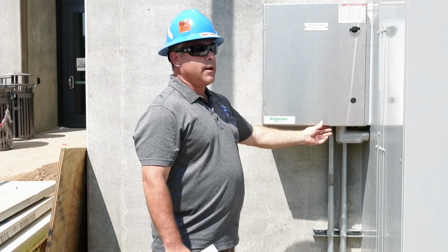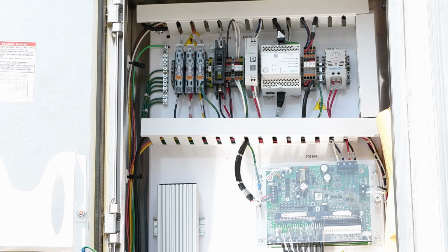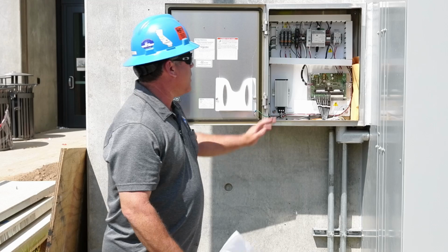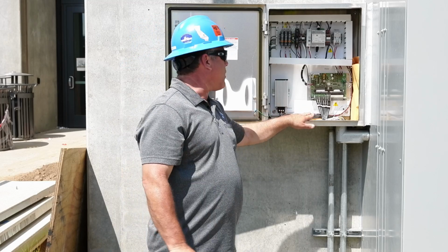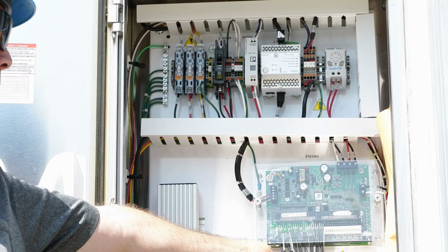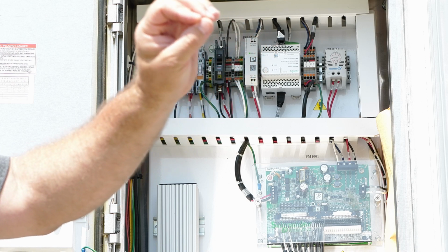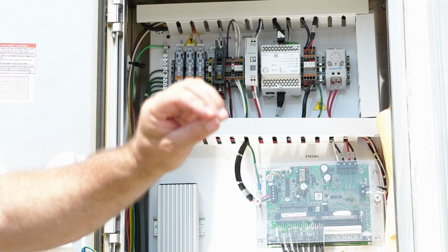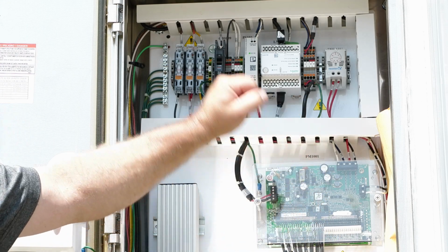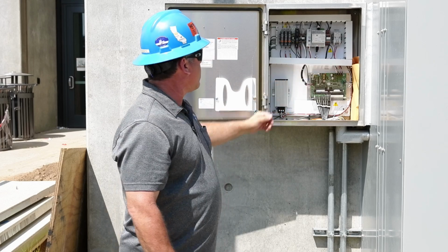This is the monitoring cabinet. So every single inverter that goes through the breakers in the distribution board ends up being monitored here inside of this cabinet. So this cabinet is remotely monitored by the Schneider software, and every single current transformer that was placed in each breaker in the distribution board is going to end up in this little circuit board. From here, it goes to the remote station and it can be remotely monitored through the program.